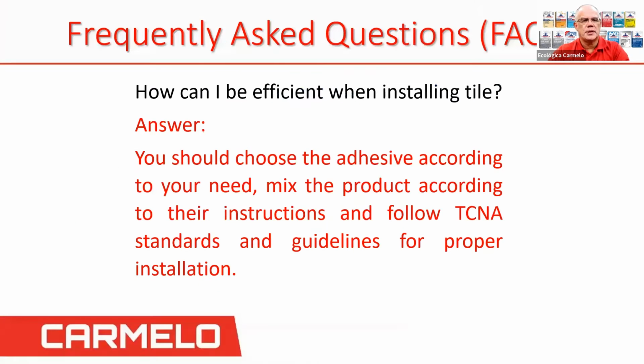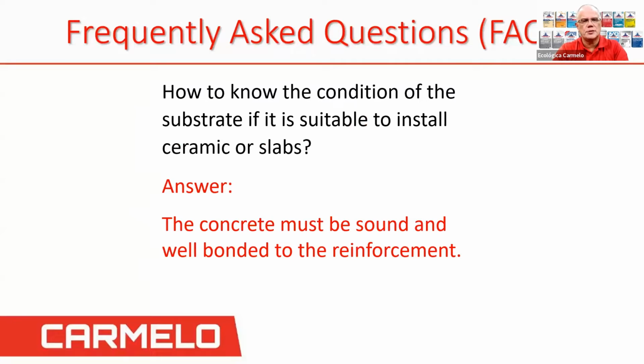So let's get going. Let's ask ourselves, how can I be efficient when installing tiles? You should choose the adhesive according to your need, mix the product according to the instructions, always read the instructions, and also follow the Tile Council of North America standards and guidelines for proper installation. So that's very important, right? Before doing a job, read your instructions.